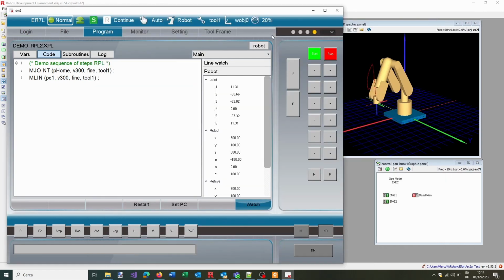And so here again I can modify the feed rate to 100%, I can press start, and here I have no need of the dead man. Remember, in case the project is not good, I will need to press the red button in case of emergency, or if I want, I can just press stop like this, and the robot will hold. Pressing start will make it continue its movement, so it's like a start and stop and hold request.